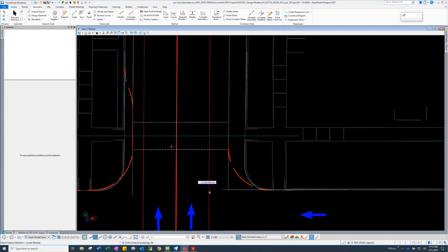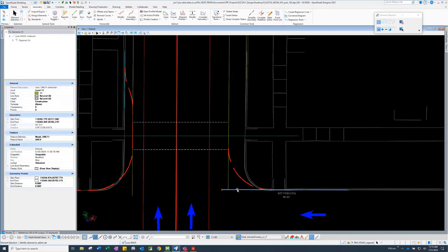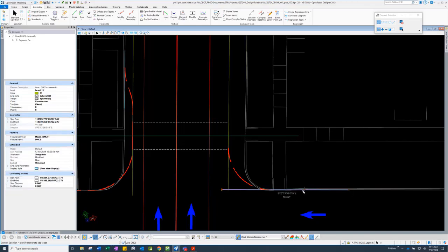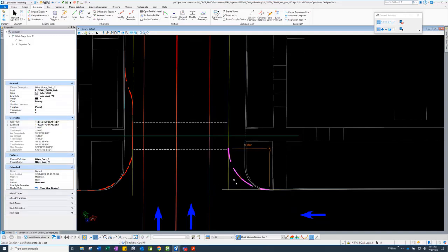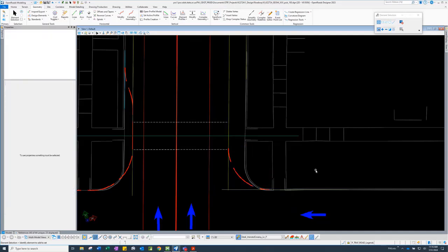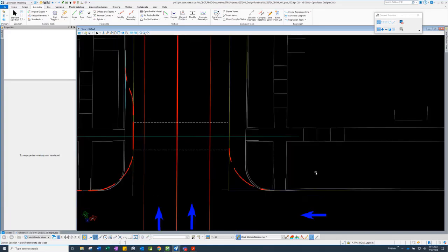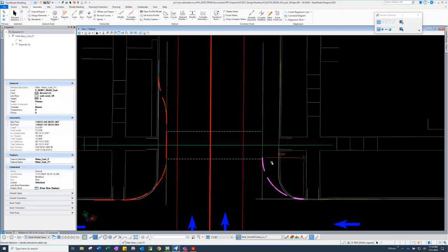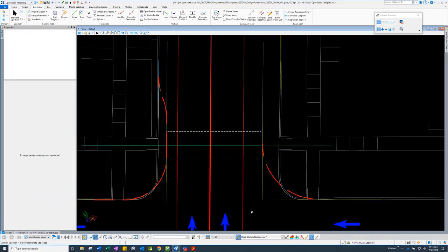Last time I showed how to draw for corner lines, a 2-point line with the extend, and then a partial offset with a curve. Now, part of the way to check these curves is, I got to thinking, we need to make sure that the truck turns. So is this the right radius? Let's set this now. We're going to put in 20. Okay, we're going to do a 20, and is this the right radius?